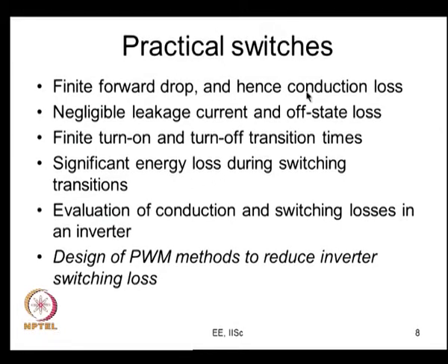So, we evaluate conduction loss and switching loss, etc., and today we are hoping to design PWM methods which would reduce the inverter switching loss significantly compared to something like sine triangle PWM or conventional space vector PWM. I would emphasize the fact that there is a reduction in switching loss, not really conduction loss, but